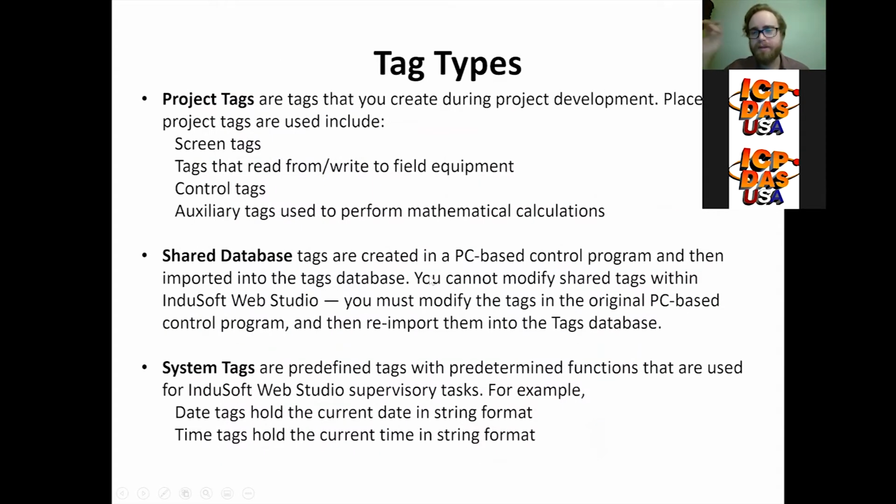All right. So we've talked about the different licenses and thin clients, and I've mentioned tags a couple of times, and I assume that many of you are familiar with what a tag means in this instance, but in case you're not, I'd like to get into the details a little bit. Tags are a core component of any Indusoft Web Studio HMI project. Simply put, tags are variables used to receive and store data obtained from communication with plant floor devices, from the results of calculations and functions, and from user input.